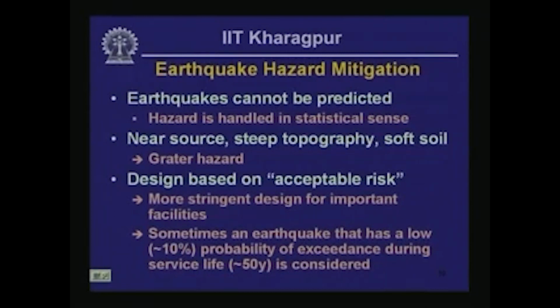Thirdly, and as a consequence of the first 2 points, really, design is based on the notion of acceptable risk. What is meant by that? What is meant by that is you have to go for a more stringent design, or more stringent requirement is placed on the facilities that are to be constructed in areas that are more hazardous in comparison with areas that are relatively less hazardous.